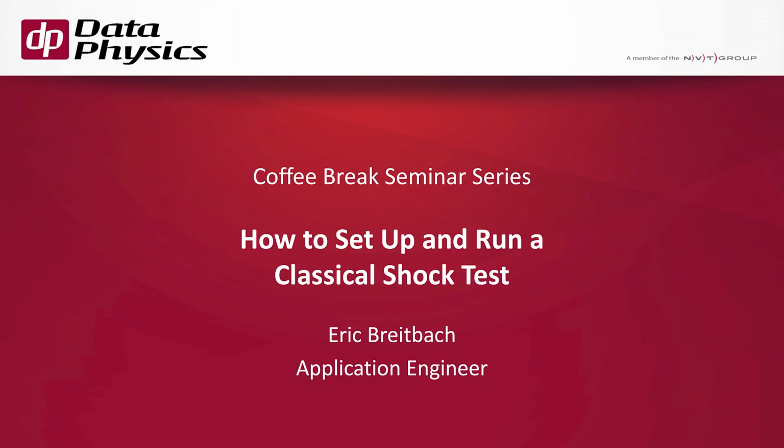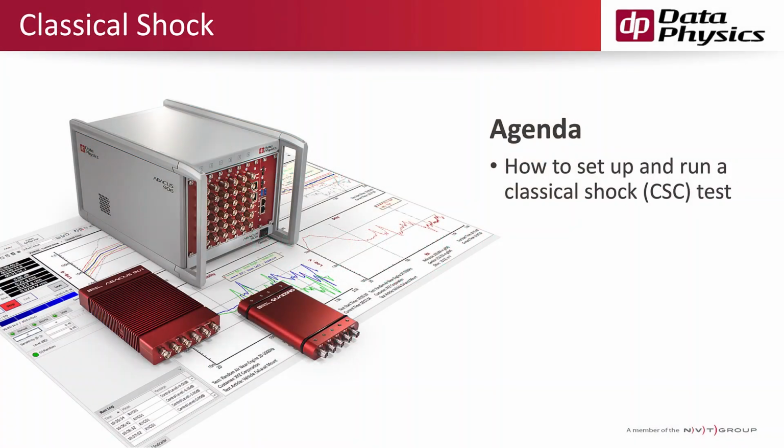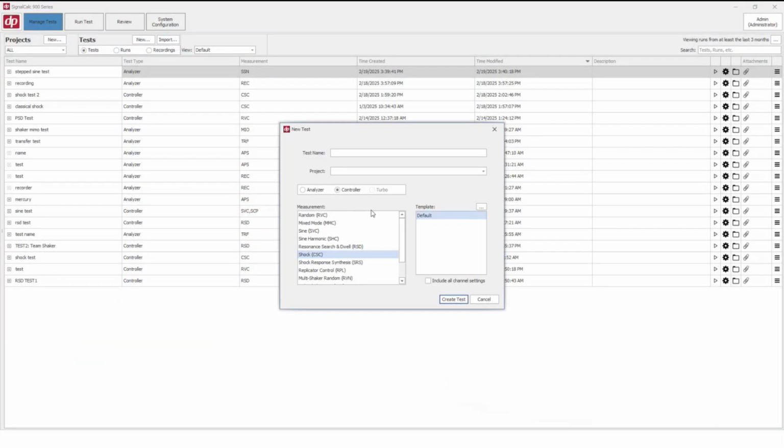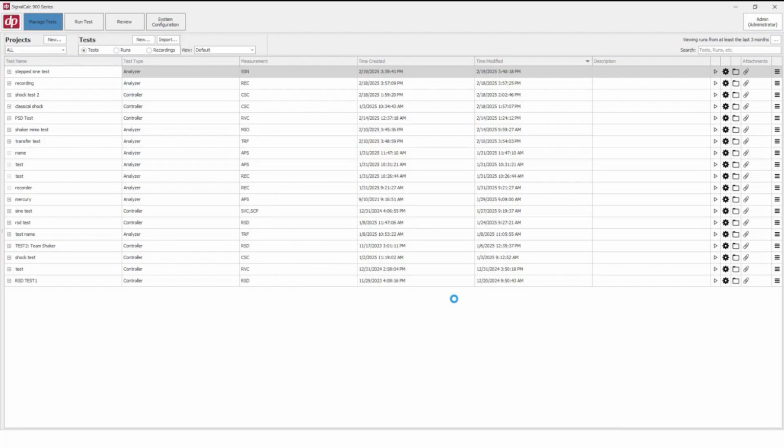Today we're going to be talking about classical shock testing. The agenda for today, we'll cover setting up and running a classical shock test. Let's dive into it. From the Manage Test, we'll just hit New Test. We'll give it a name, and we make sure we have shock selected.